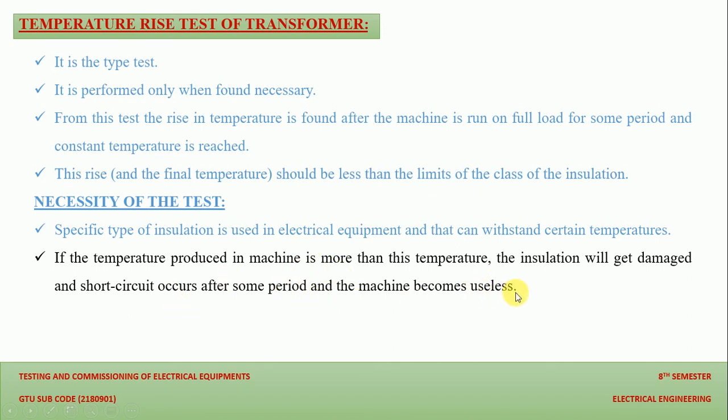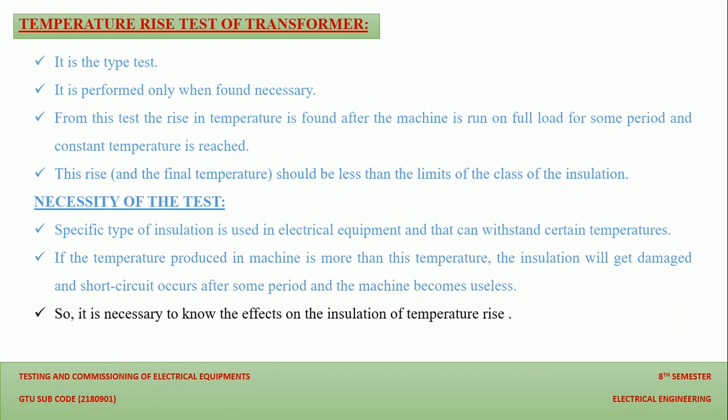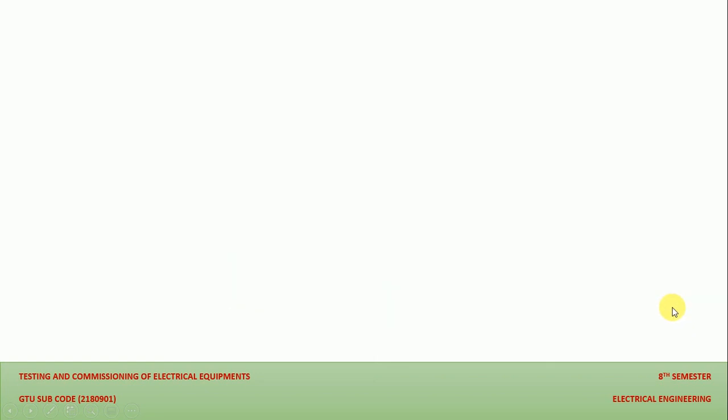As I explained, if the inner temperature increases beyond its limit, the insulation will fail, and there will be chances of short circuit between the live parts of the transformer. So it is necessary to know the effect of the temperature rise on the insulation, which we need to check. This is the necessity of the test.